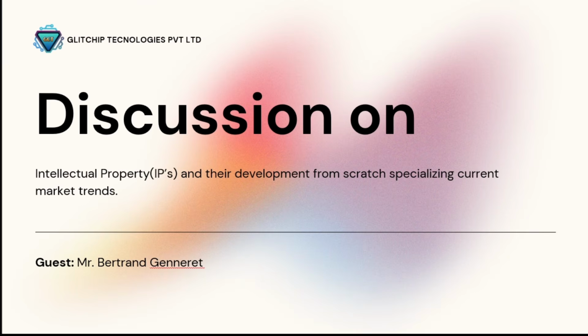Then you have design for test, DFT. In this step, you implement the test structures. It's at the same time as synthesis. You're doing some DFT structures such as scan chains. This guarantees that your IP can be tested during manufacturing. And it means that the inputs of your IP should be controllable and the outputs observable. And then, I'm moving from soft IP to hard IP.